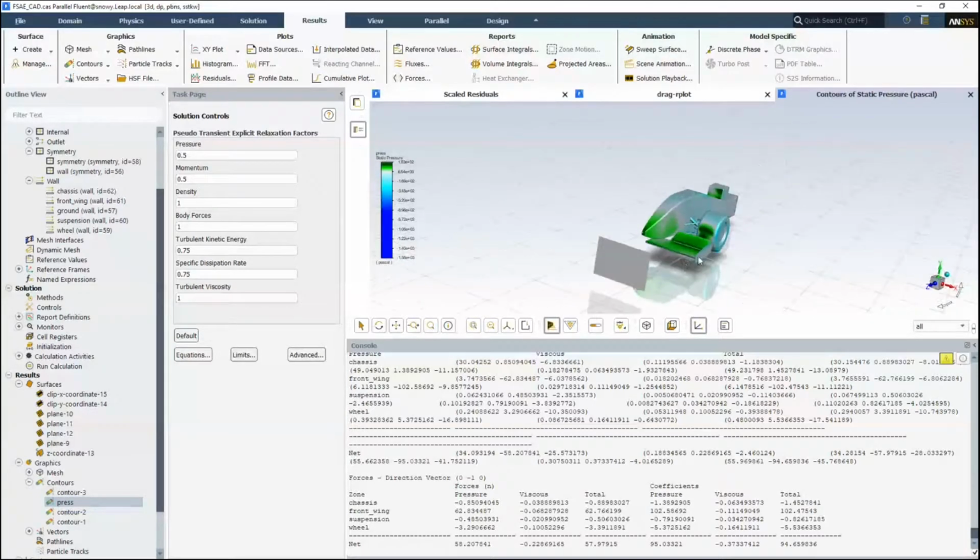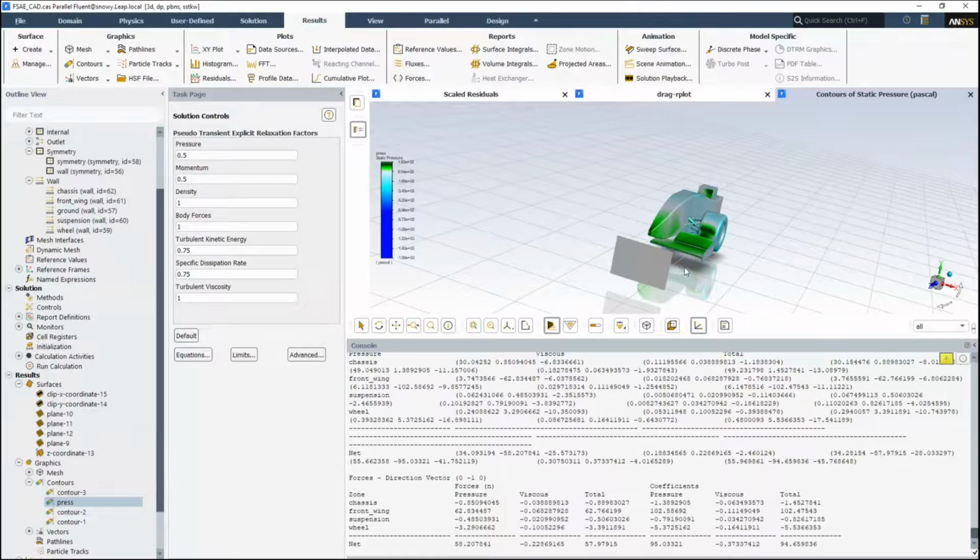You might want to make it smaller. Say you really wanted to understand what was going on with the flow around this end plate. You might make a really small one just here, so you know that the flow you're analyzing, the streamlines, are coming straight off the end plate. You can see what they're doing, but we're going to do a very general one here.